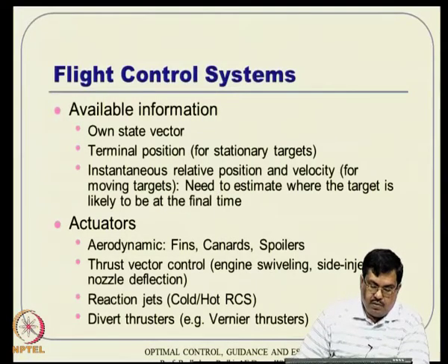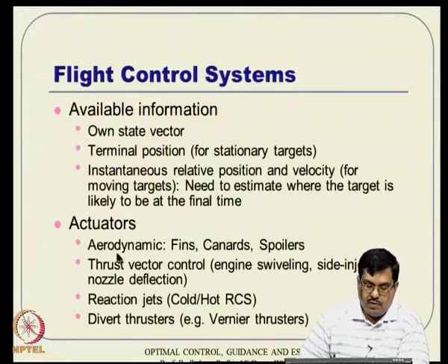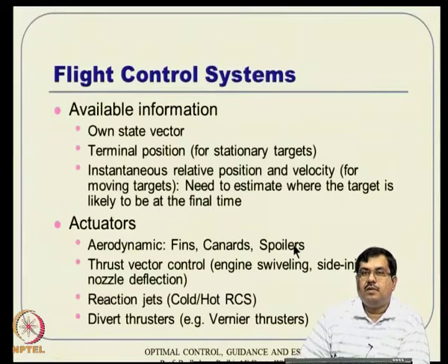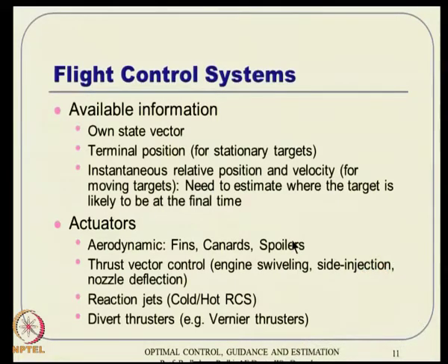Then there are actuators. We have various types of actuators. We have aerodynamically controlled actuators, such as fins, canards, spoilers and things like that, which are typically useful within endo-atmospheric engagement, where you can generate lifts and moments and then manipulate them. These are very good, because these aerodynamic forces and moments are available almost free.